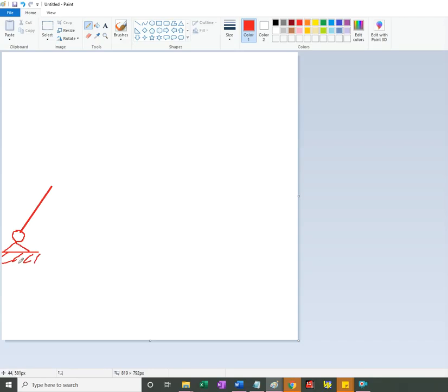I have the ground and the actual link, 2 links and 1 joint with 1 degree of freedom. Mobility is 1. If I come in with the RRR dyad and put it in place, and then connect to the ground, I get that good old 4-bar.